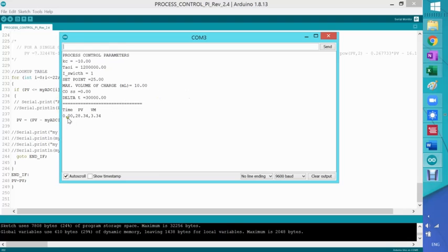So you get the time, the actual temperature, and how much cold water you have to add to your hot water just to bring that within temperature of 25 degrees C. The time here is every 30 seconds. This is 30,000, but this is milliseconds, so I better write the unit here. This is 30 seconds, and it prints every 5 seconds until it hits the 30 to let you know that you need to again add 3.83 mLs of water to your hot water.